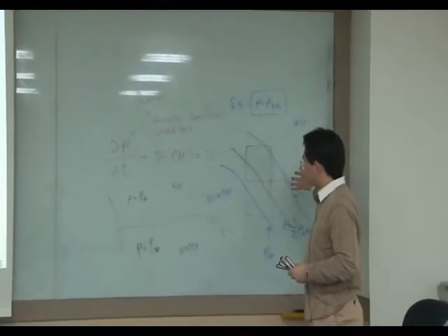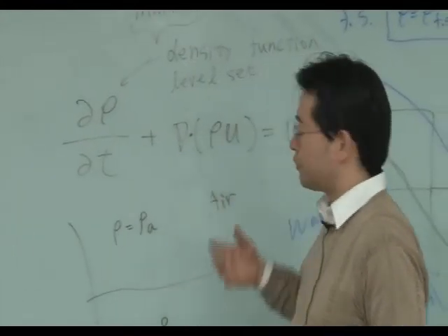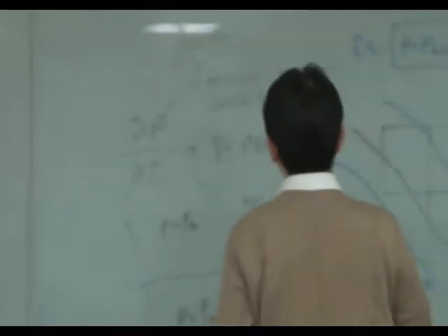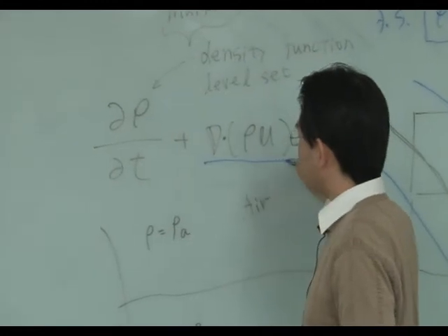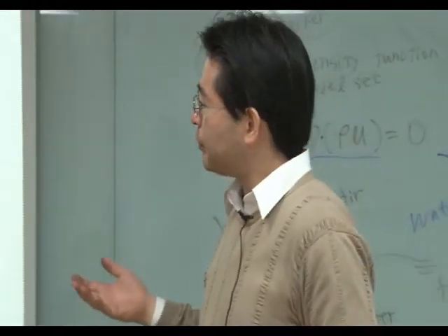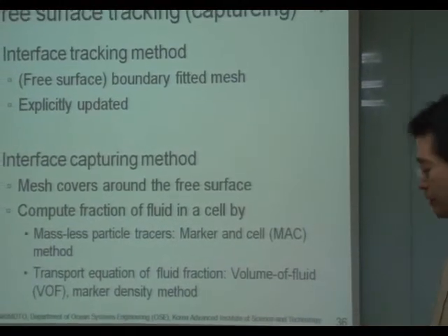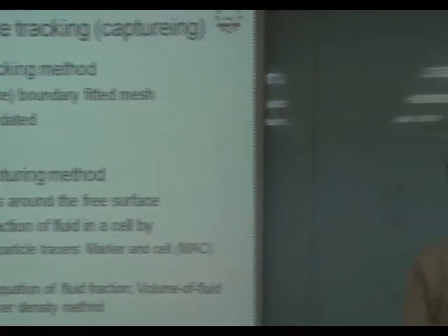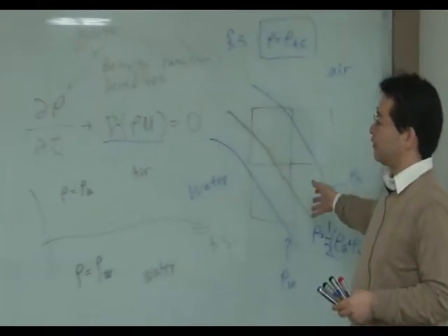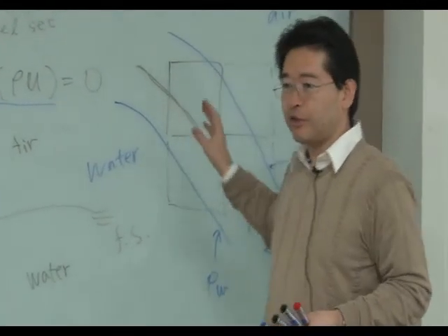Actually, this is almost equivalent to the convection calculation. So the convection term requires an upwind scheme. As I said, the upwind scheme shows diffusive capability for stabilizing the fluid motion. But diffusive capability is not good to keep the thickness of the free surface.